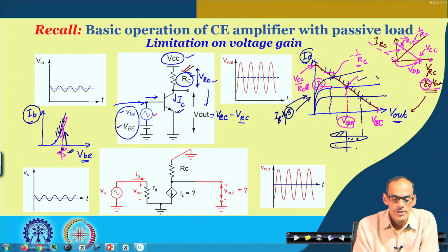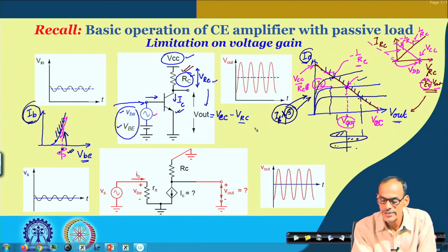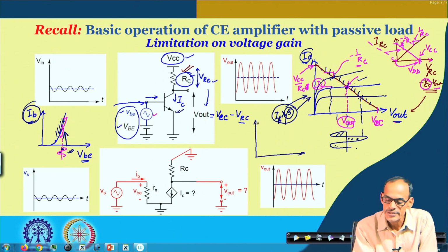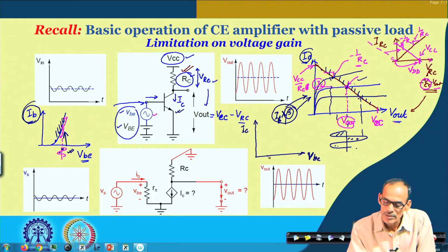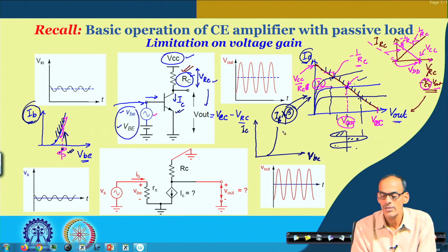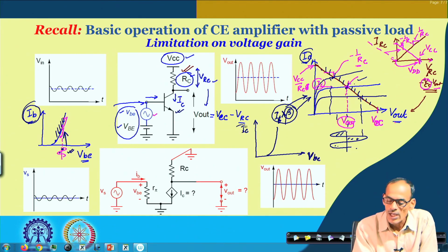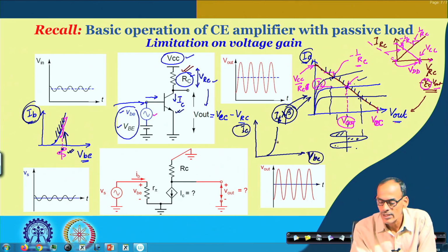In fact, if you combine this multiplication and the exponential relationship, namely if we plot the IC versus VBE characteristic curve, then of course this is also exponential, but with a different scale because of the beta. So, this IC versus VBE characteristic curve gives us one conversion from voltage to current.